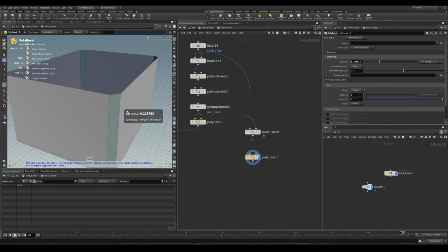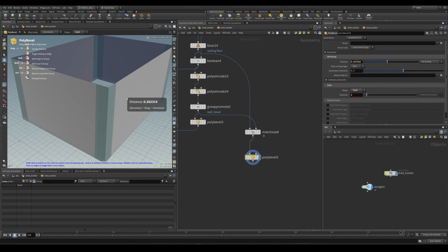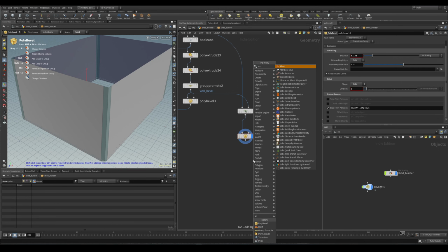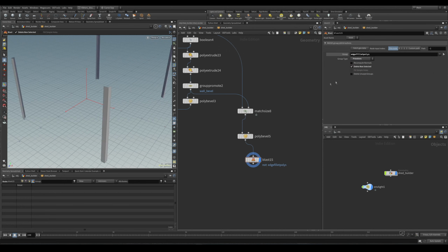and this bevel, it's automatically going to start to bevel it like that. What we'll do is make sure that we use a solid bevel, and division is going to be 2, and this parameter is going to choose how big of a trim we want for our corners like that. And also want to make sure that we also edge fillet polygon group create, and then just blast it. So we blast it, so our edge fillet polygons, that's going to be primitives.